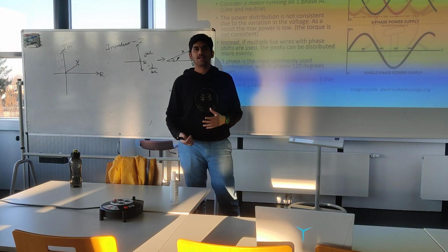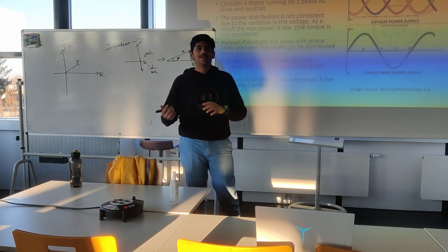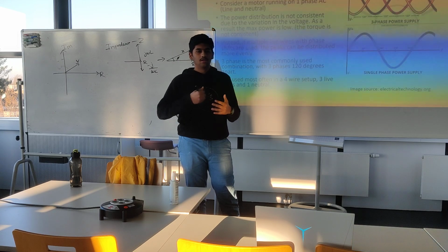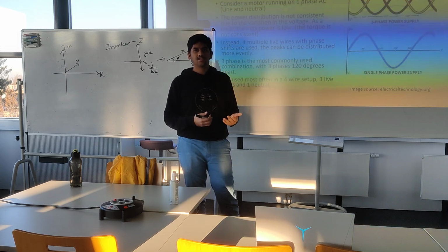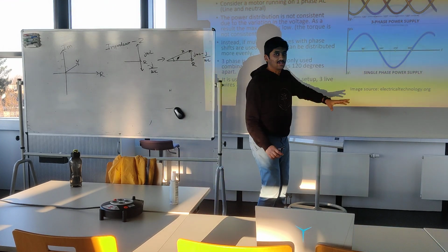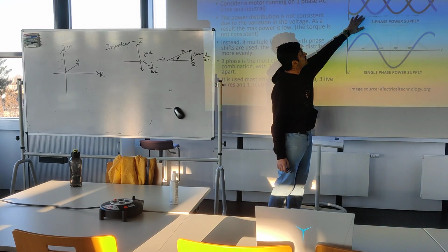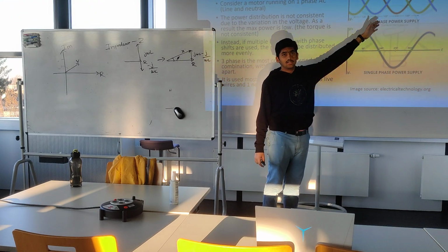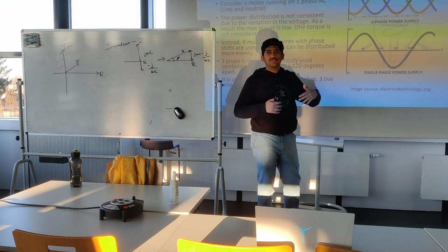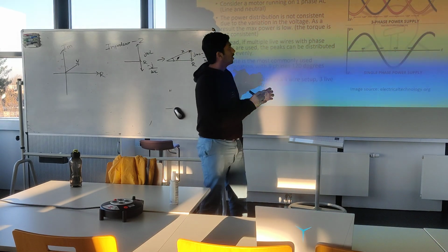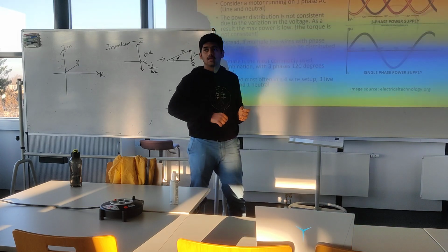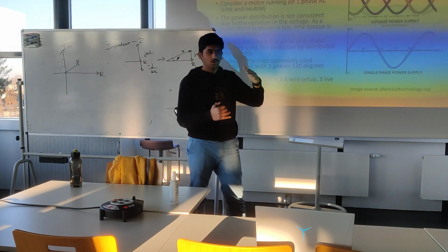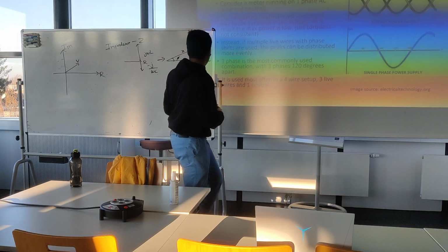But today, the power demands have shifted. We have a lot of appliances which use DC, and they have their own internal AC to DC converters. So this is not relevant for them. But for a motor, three-phase is fantastic because you have a much more consistent current delivery, which means you have consistent flux, which means the peaks and troughs of the torque are lower, so the torque is more consistent.